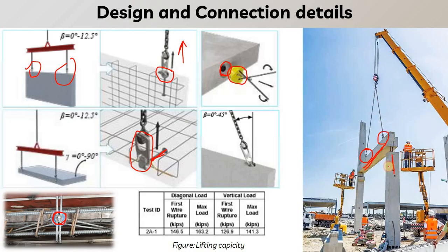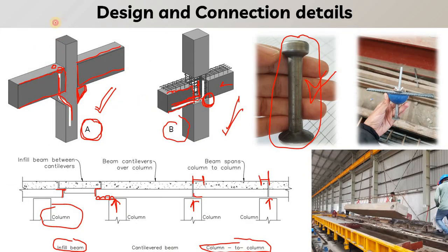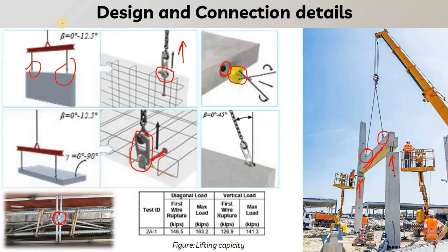So now this is the precast column that is placed in position, that has the corbel connection. So it will be a kind of type A connection. So we have this kind of connection that we are looking into. Here you can see this is the corbel connection that is provided, and from the corbel there are two reinforcement bars coming out, that will be connected through the double tube provided in the precast beam.